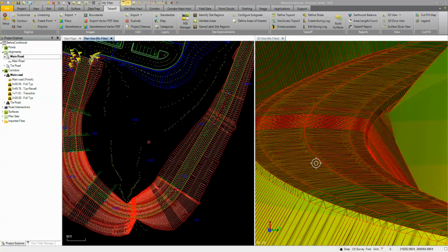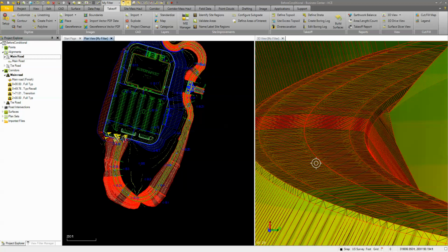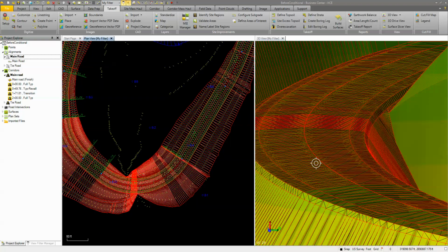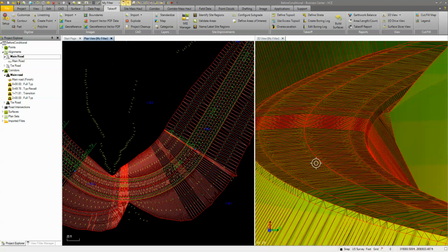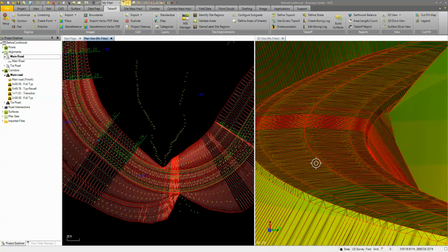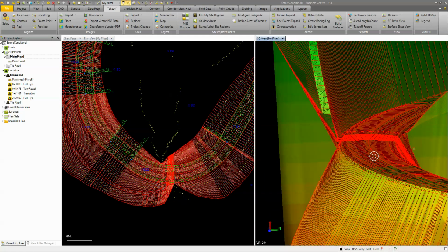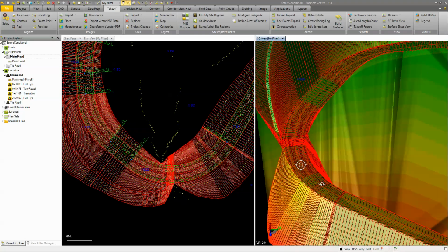So another edit that we have to make to our road corridor is we want to add in some super elevation along our corridor. We're not too concerned about these curves over here, but we're definitely concerned with this one. We want to put a pond here, so what we want to do is be able to capture this flow off the road along this curve and dump it this way. We've got a ditch coming down here where we'll have a catch basin that will catch the water and push it over to the pond over on the inside of our site over here.